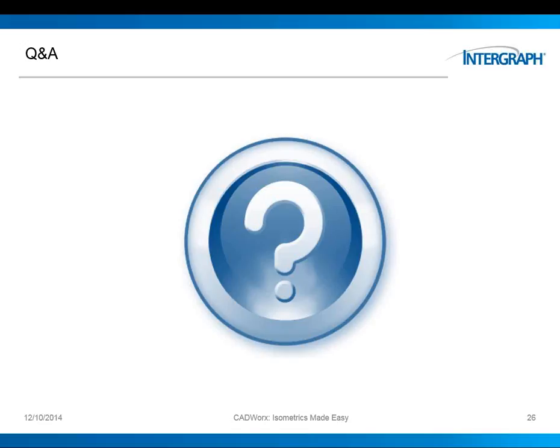Thank you. Can I use Isogen to generate ISOs out of session, i.e. outside of the piping application? Okay, interesting one. Isogen can only be used within CADWorx or any other application that is bundled with Isogen. So for example, PDS, Smart 3D, and Caesar2 all have Isogen. In order for you to perform out-of-session processing, you need to export PCF files from the CADWorx model and feed them to Spoolgen. Unfortunately, the high cost of Spoolgen may not justify it unless you have a large number of spools to process.